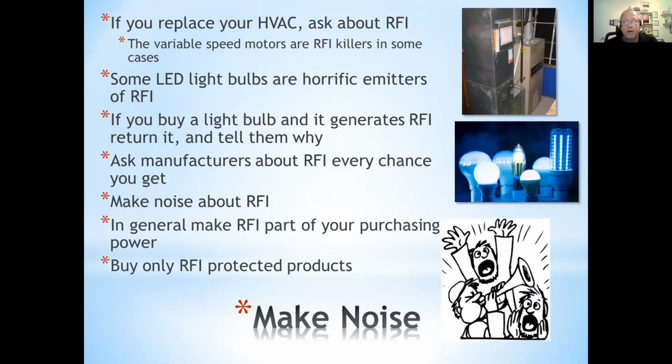When arc fault circuit breakers, not circuit breakers, wall outlets came in, right? They became mandatory for bedroom use here a few years ago. The first ones they came out with were horrible at being susceptible to RFI. You'd get on 40 meters and it would start tripping all these GFI breakers in your house, all these arc fault ones. And there's certain ones now that you can buy.